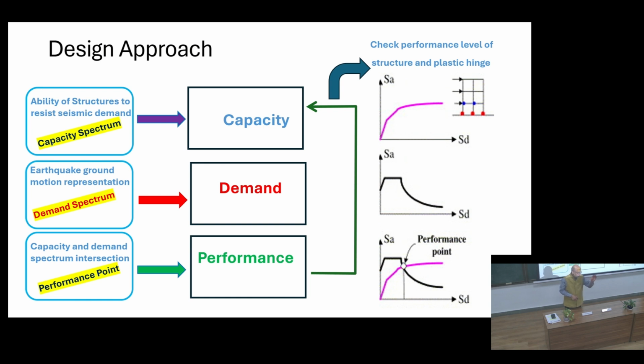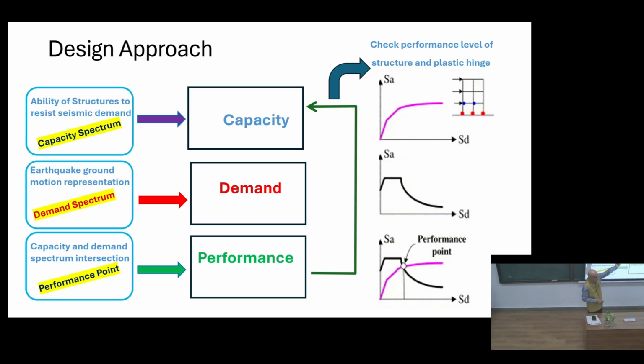When you solve the equation for the equivalent single degree of freedom system, you get this curve. So it is a smooth response of a large number of earthquakes. You cannot go to the highest level, and you are not at the lowest level either. So in the middle of this you have to fit. That is why you take 100 earthquakes, 50 earthquakes, or synthetically generated earthquakes, depending on the place and requirement, and then you fit it.